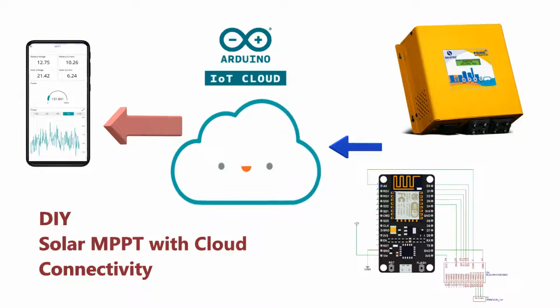So I was able to figure out these lines. The next idea was to read this information and find out how the divider is working, I mean how much voltage division is happening for the solar as well as the battery voltage, and similarly for the current.